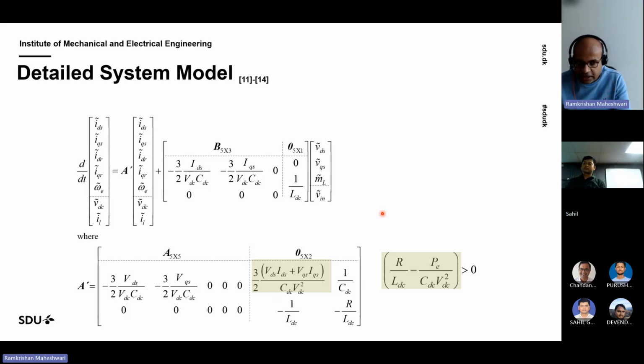As soon as you have a large disturbance, it will try to draw some power from the capacitor. Since we do not have any storage on the DC link capacitor, the same thing will go on the grid side, and then the system does not behave very well. So not good for a sharp change in the load torque. Okay, for pumps, fans, fine.